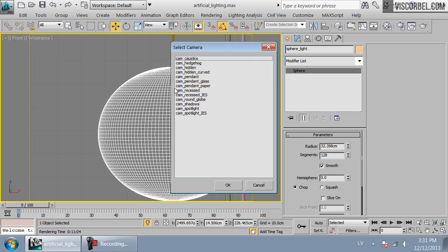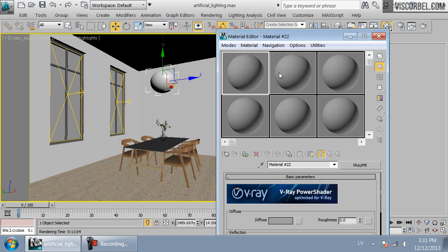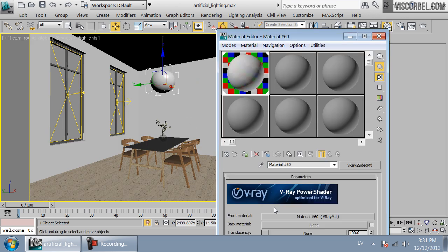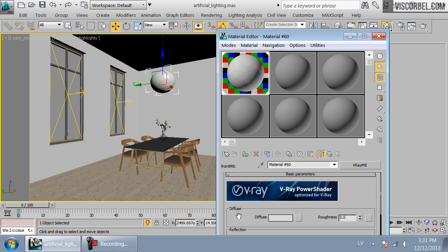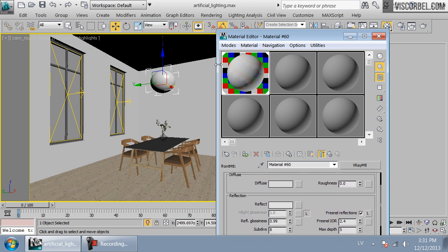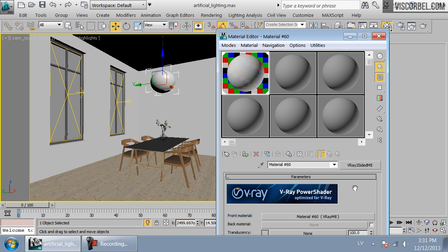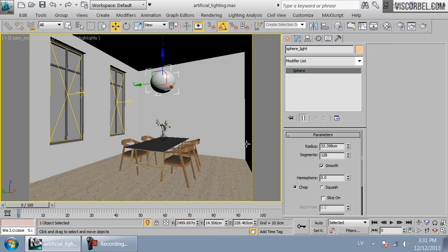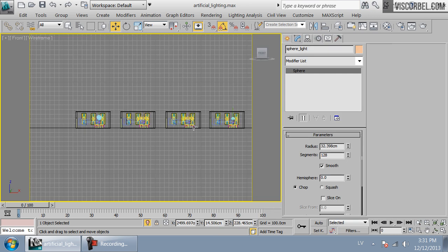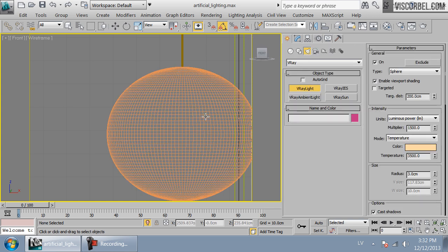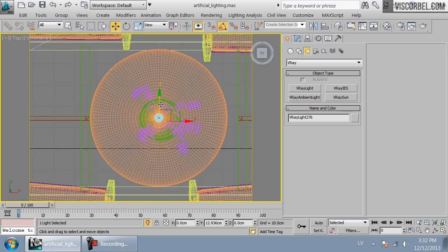So in this case I recommend creating a new material. So here's the material for the lamp, and basically it's just some simple glossy white V-Ray material set up as V-Ray two-sided to give it some translucency. And it's going to render quite fast. And in this scene I'm going to use two lights. So one bulb will be used to light the lamp itself. So let's say 3 centimeters, 1,500 lumens, seems about right, position in center.